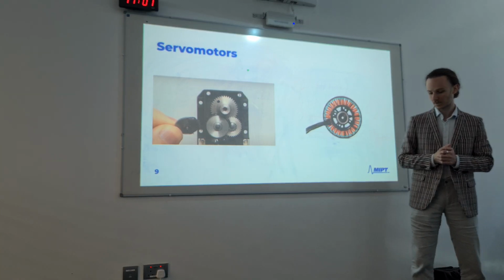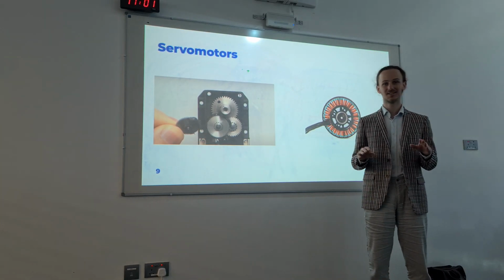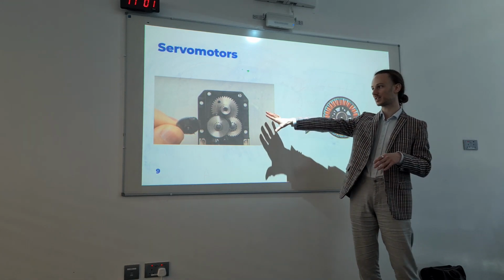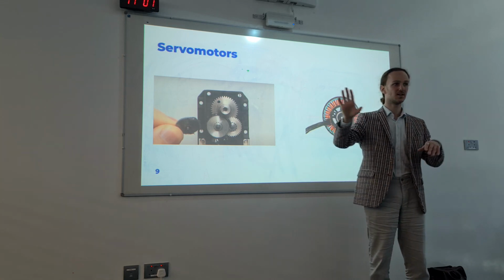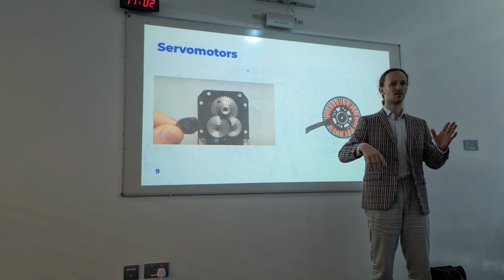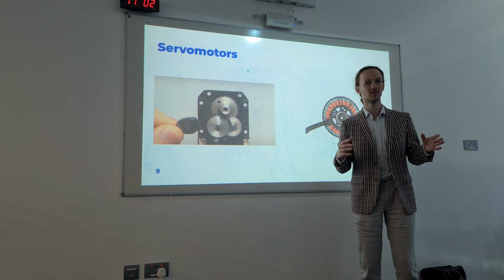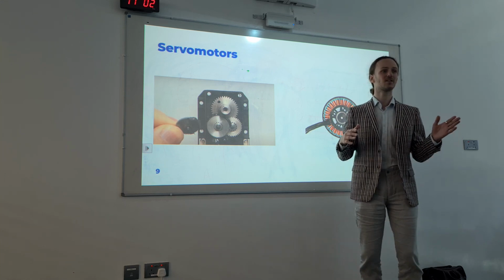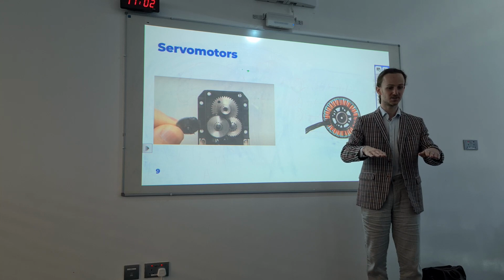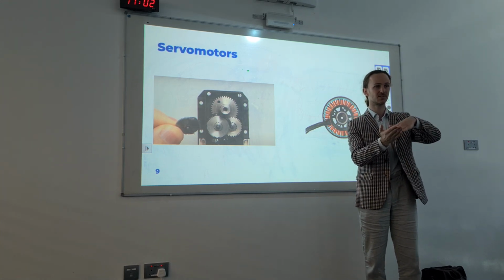And I was jumping with awful sounds on purpose. If the robot is jumping with this type of servo motors, they cannot really react and roll back so that they don't get this hitting impact. So let's take a look once again. Here I'm jumping normally, and my feet are reacting to the moment of contact with fast enough motion.